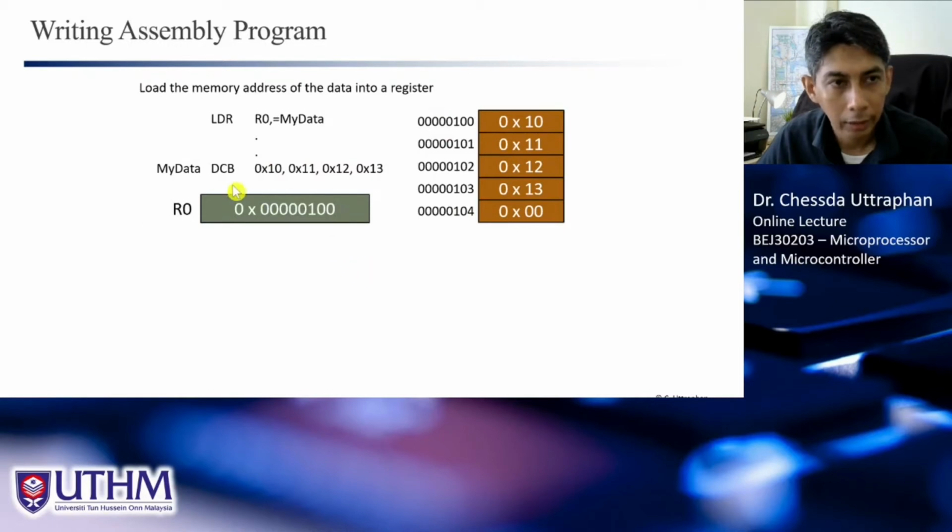Okay, we can also use this instruction, LDR R0, =my_data. So this is new for you. Last week we learned LDR, the load instruction that loads data from memory to a register, right? Last week our load instruction had the memory address in a register, so that we could load the data pointed to by that address.